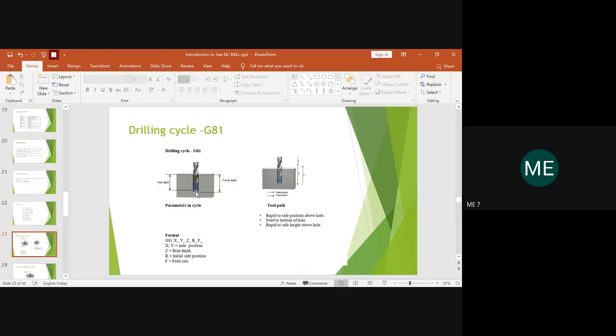Remove the tool safely so that it won't damage the surface. For that, it should be moved safely in the upward direction. If you want the tool to move safely upward, you should provide an initial safe position so that it moves away from the blank. After it moves away from the blank, you can send it to the home position and change the tool. I mean to say that you make sure the tool is removed safely from the hole without causing any damage to the blank or to the hole which has been formed. That was my meaning.